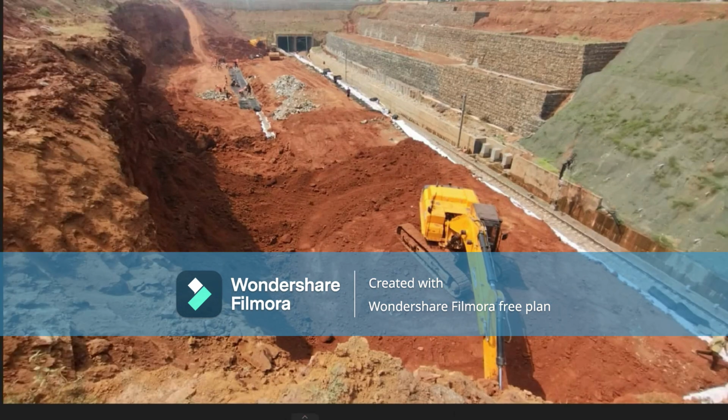We can see here that three berms, one, two, and three, are provided to stabilize this steep slope. This is a steep slope. It has failure, due to pore water pressure and during the rainy season. This is the left hand side, and this is the right hand side. The left hand side was constructed first, and then they started the right hand side.